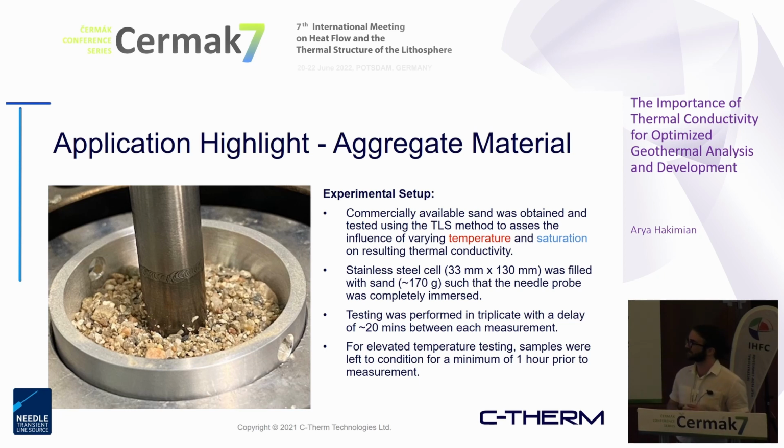Now, you can see the image on the right. The needle probe is fully inserted down into the sample matrix. And with this material, it's quite ambient temperature, ambient pressure. There wasn't considerable environmental control adjusting these types of parameters. But one thing to take note of is that as the measurements are taken, a fixed delay is introduced to ensure that with each measurement, you're not introducing significant additional heat into the sample, other than what is needed for the actual measurement.